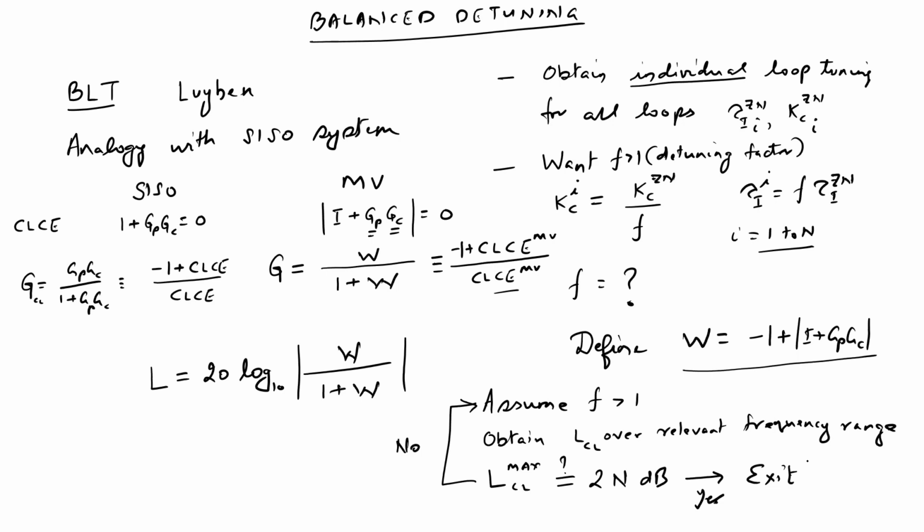Of course, with the tuning that you get with this procedure, you usually need to confirm the closed loop performance using simulations, and one must treat the tuning that you obtain just like in Ziegler-Nichols. Tuning is also indicative. Sometimes it can perform very poorly even for SISO systems, and the tuning rules that you apply get you an initial ballpark. So this procedure will also get you an initial ballpark tuning for each of the loops. You may have to fine tune the tuning a bit more.